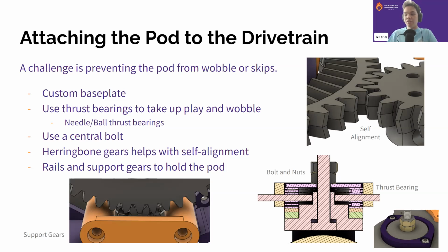So currently we're using robot-centric. If we were able to solve the issue, we probably would switch to field-centric because that'll make it a lot smoother in terms of scoring and stuff. But if you do try field-centric with swerve, keep in mind it is not easy to do, and that issue is very persistent. So again, we'll post that paper we found about how to kind of solve it online along with the presentation. In terms of just implementing it, it is practically the same. It's just that one issue shows up that makes it a lot more difficult to use. Just to clarify.